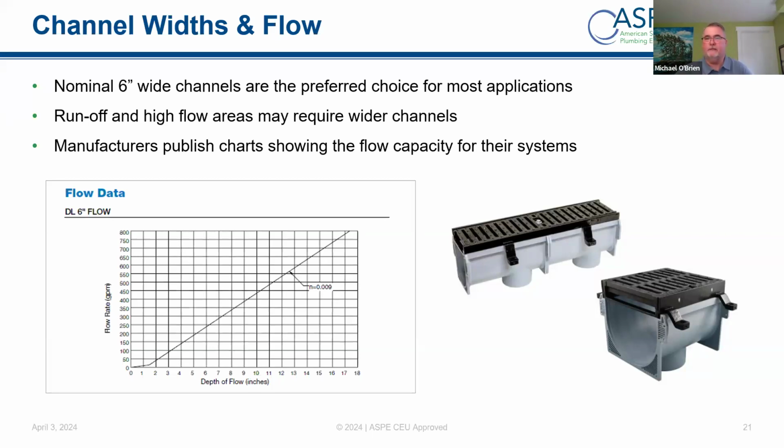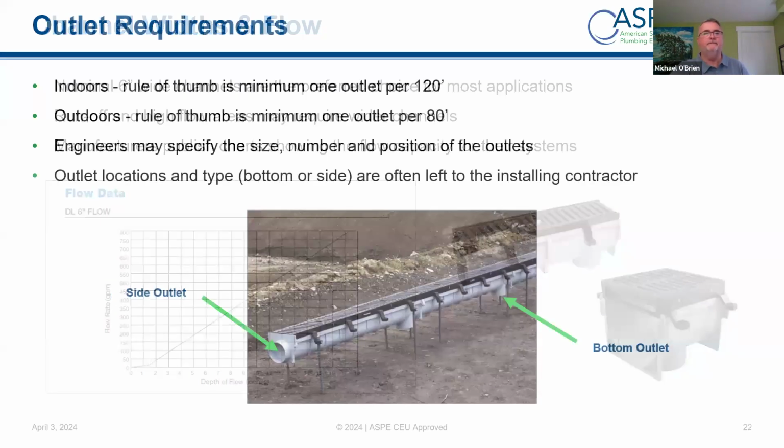And if there's a catastrophic spill, it will end up in that trench drain. They can then treat that water to make it meet the requirements to dispose of it to the municipality, or have a sucker truck come and take that out and treat it. But all those things are available from every manufacturer. Again, something to keep in mind if there's the possibility that there may be a 100-year storm entering that area, and you want to be able to contain it. You can figure out what that process would be.